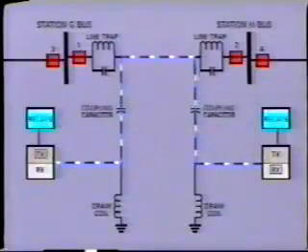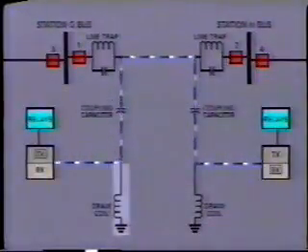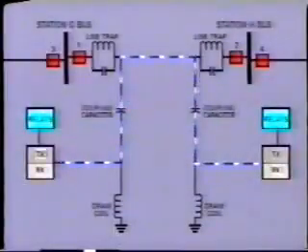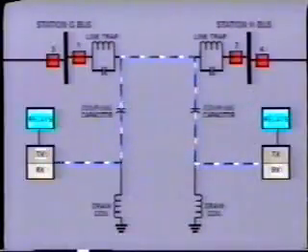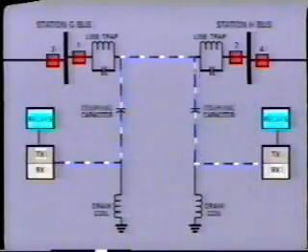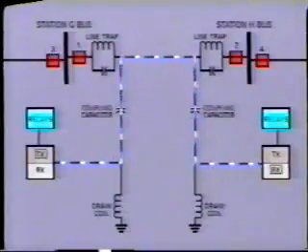In essence, the transmitter voltage signal is applied across the coil between the line and ground. The signal current circulates through the power conductor, out to be captured by the receiver through the coupling capacitor at the far end. This is where only one power line conductor and ground is used to conduct the carrier signal.